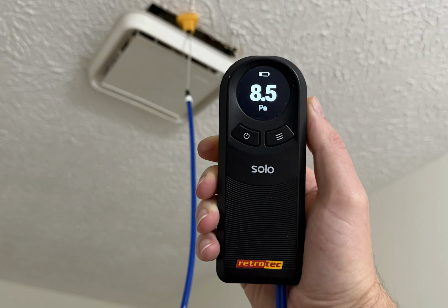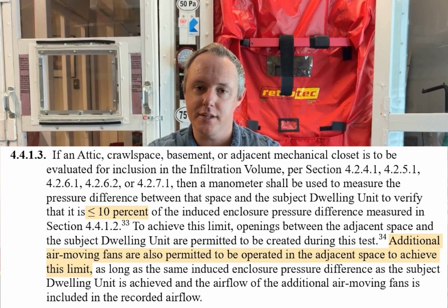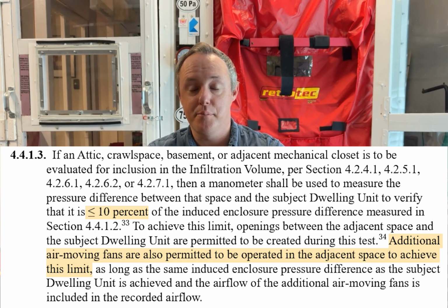So if you run your blower door fan, you probe the attic, and you see that you are not getting pressure uniformity with that attic access hatch open, you can either stop there and just not count the attic as part of your infiltration volume, or what ResNet allows you to do is force that attic space to reach the same pressure as the rest of the house, and you'll need an additional fan to do this. So if you're not getting pressure uniformity, ResNet does allow you to hook up a booster fan to that attic access and neutralize it with the rest of the house.